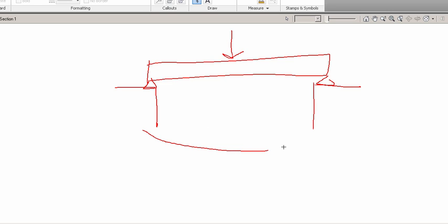and you stand in the middle of it, what's it going to do? Well, it's going to deform like this. It's going to bend downhill, right? That makes sense. It's going to sag. Perfect sense, right? Now, the reason it does that is because of the material properties associated with the beam and also its overall shape. You see, shape and material make up the real nuts and bolts of why things perform structurally speaking. And if we were to look at this beam, we would find out that some of the greatest stresses of the beam are occurring at the very top and the very bottom of the beam.